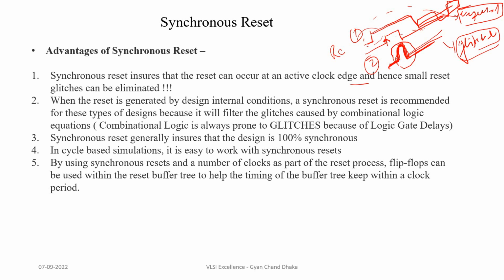Similarly, the first advantage is based on an external reset. If the external reset is glitchy or there is noise on the external reset pulse, then the synchronous reset will make sure that any kind of glitches or noise will not affect the design. Similarly, if we do not have an external reset and the reset signal for our other flip-flops is generated internally, then also using the synchronous reset we can make sure that any glitches generated by the combinational logic are filtered.